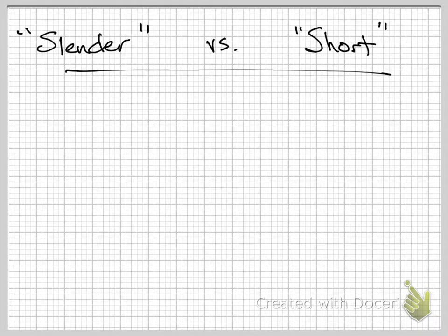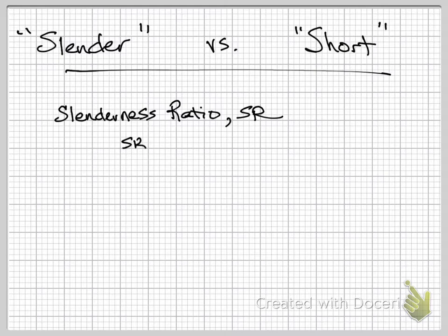We're going to use a geometric property to define this particular feature of how it behaves. And we're going to call it the slenderness ratio. Okay? Slenderness ratio is what we call the effective length over radius of gyration. Effective length being KL and R being radius of gyration. This is our equation number 2.